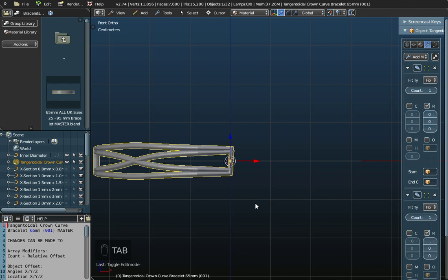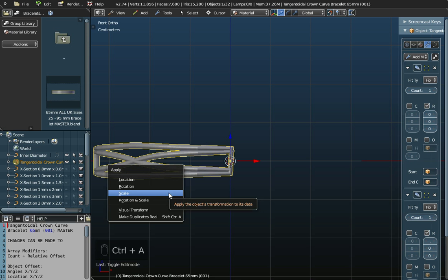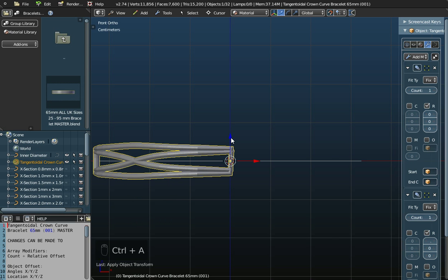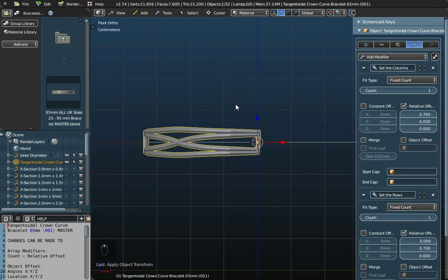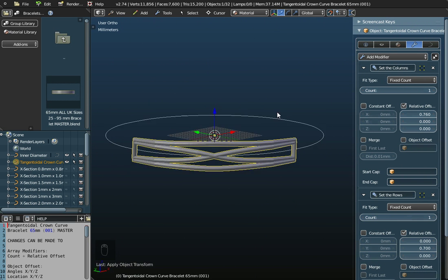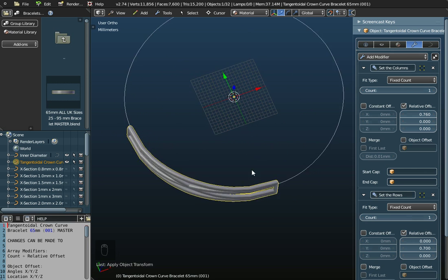Now whenever you do this in Fluid Designer with a curve, and this object is a curve, we can see that from the icon here in the outliner window. That's telling me that this object's a curve. Whenever you stretch things, always do Control A and apply the transformation. That's really important in terms of 3D printing. Now you can see what I've done to my curve.